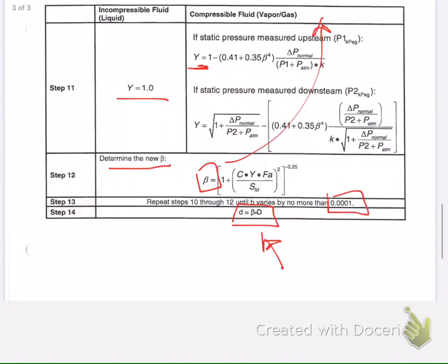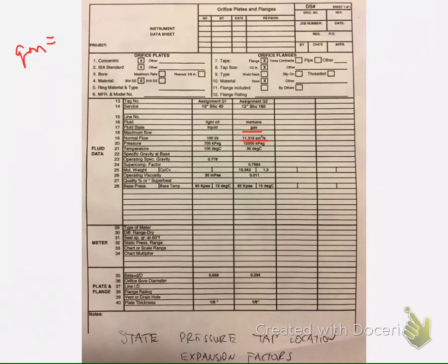Yes, so I'm just going to write that down here. Density at standard conditions is equal to 101.325 times m over 1. I don't think there's a z value given here. Compressibility. Oh, there is a compressibility factor. But you know what? We don't need that right now, because at standard conditions it should be a value of 1.